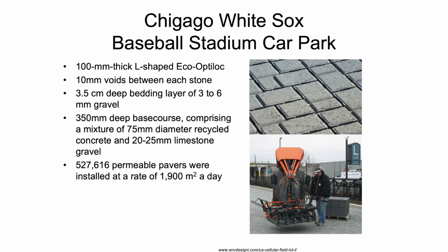They have a 350 millimetre deep base course, which is quite deep, even for such a large system, and that's because they had to take buses and heavy vehicles as well as cars. And you can see that large diameter stone in there. Recycled concrete is something we wouldn't recommend generally.